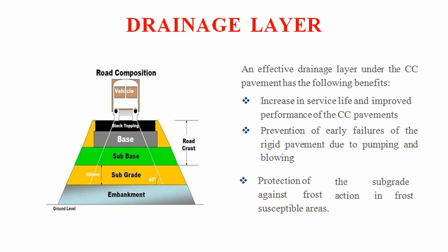Next, the drainage layer. An effective drainage layer under the cement concrete pavement will be beneficial for the following factors. First, it will increase the service life and improve the performance of cement concrete pavements. It prevents early failure of the rigid pavement due to the pumping and blowing action of water. Then, it protects the subgrade against frost action in frost susceptible areas, majorly in cold countries.